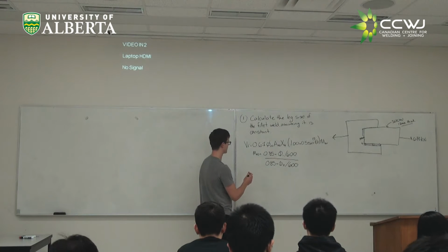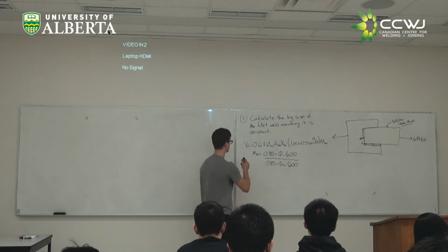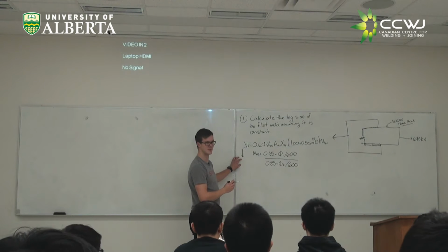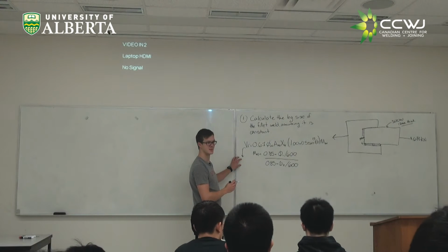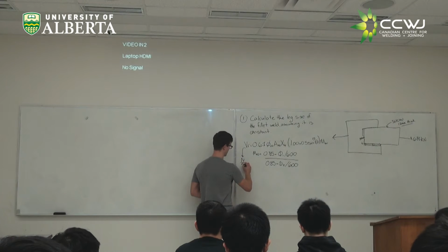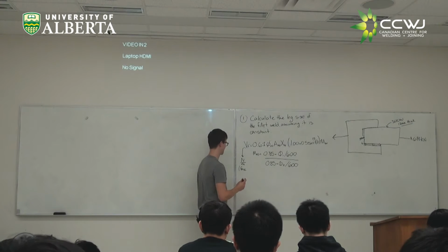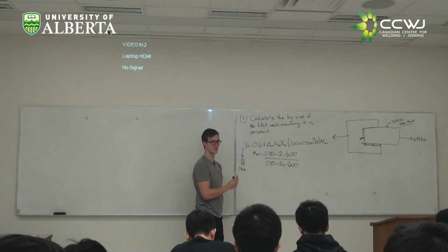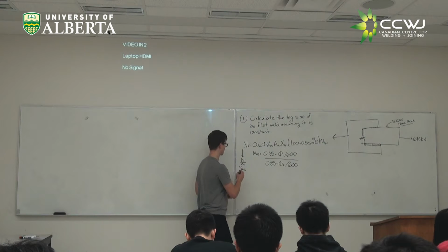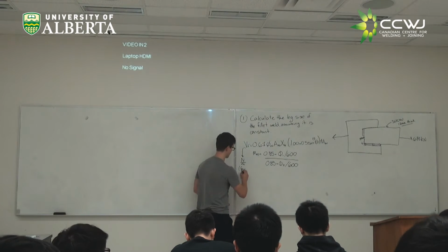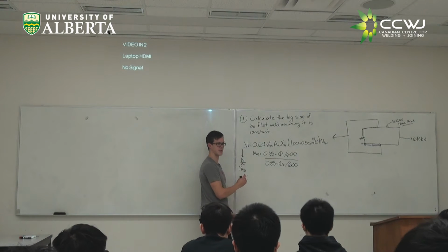One thing I think was mentioned fairly well in class, but just so we're clear, does anyone know what units this has? Right. So newtons per meter, or force per length: it could be pounds per inch, it could be kilogram force per centimeter, it could be any force per length. Typically we're going to do newtons per millimeter or newtons per meter. There are some examples which have imperial units, but it's the exact same math no matter what.